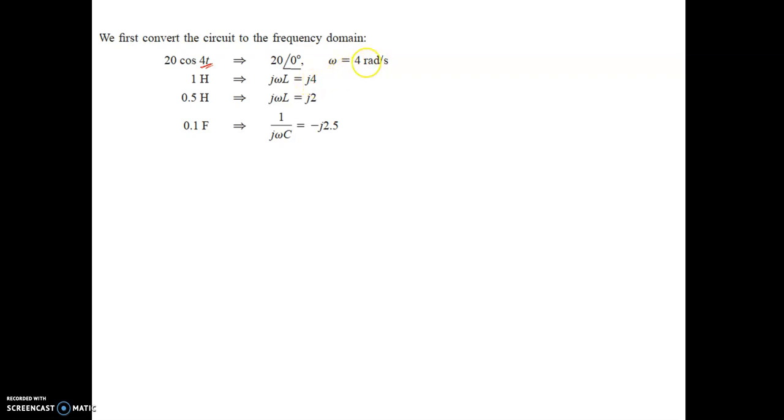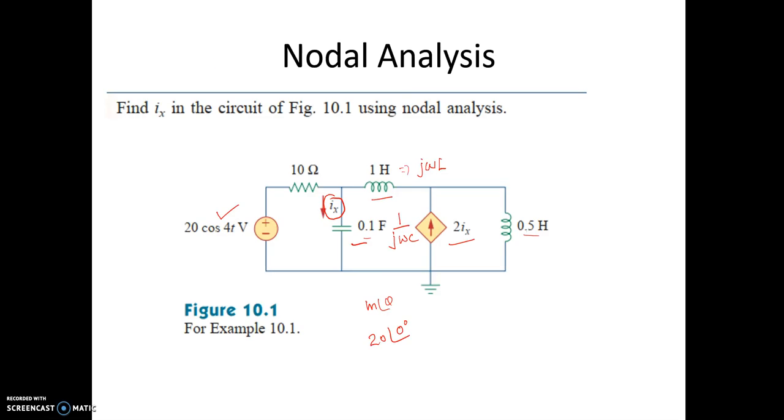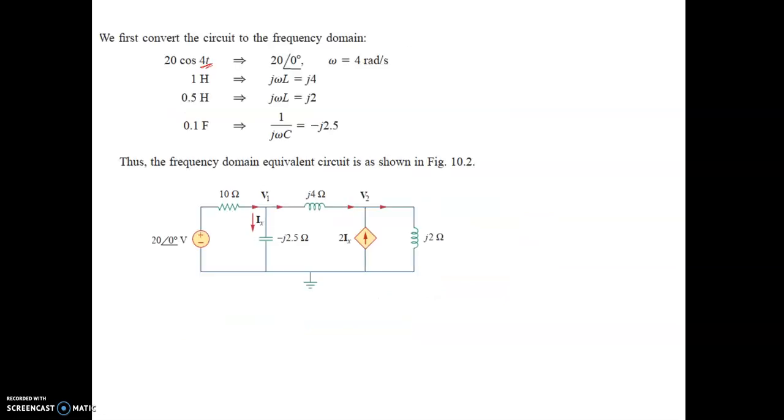Once you convert everything, you have to apply all these things in this circuit and modify the given circuit into frequency domain or phasor domain. In the modified circuit, everything that is in terms of henry or farad will be converted into ohms. j omega L is nothing but XL, j omega C is nothing but XC.